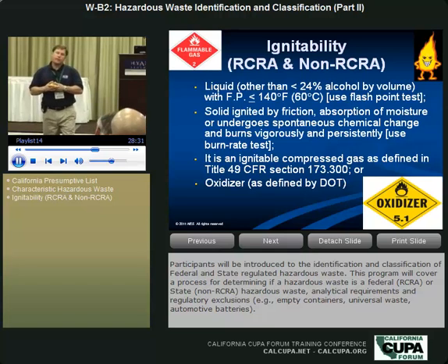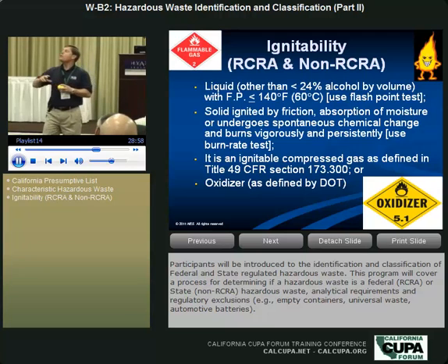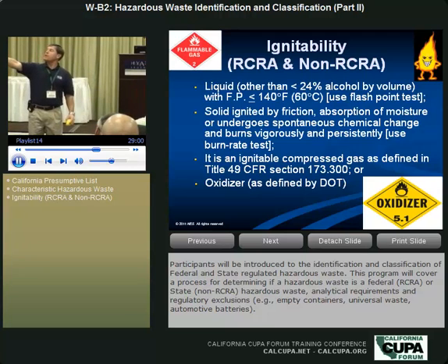Is the facility a large quantity generator subject to RCRA subpart CC requirements for VOCs above 500 parts per million? Probably not. So is it a large quantity generator? It is a large quantity generator? And it is subject to subpart CC VOC requirements above 500 fugitive emissions. So that has to be. I'm sorry? If it's a large quantity generator, is the container greater than or less than 42 gallons that you put it in?